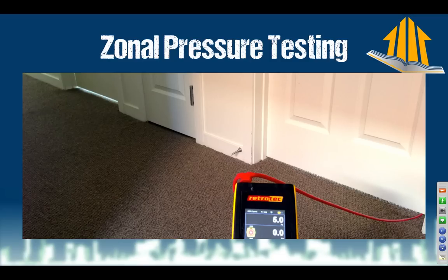There are a million ways you could say this, but I find that that's the easiest way to express this to somebody who doesn't understand how this test works. You just say, that room has a 10% connection to outside, this room has a 5% connection. Therefore, we're going to really focus our work on air sealing in this room that's got the bigger connection.